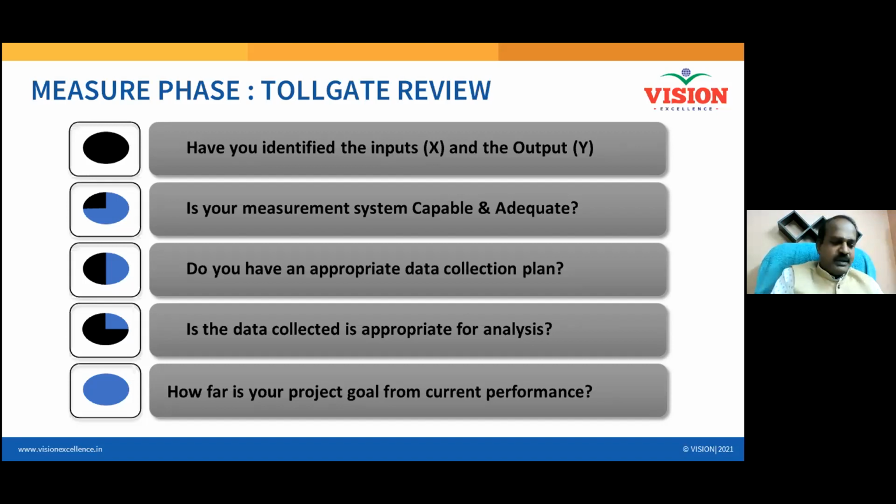In the same way, when you collect data, let's say from 100 to 110, all your readings are going to be from 100 to 110. Within the 100 to 110, how many readings is your system going to give you? That will talk about the adequacy. And suppose my resolution is 0.1, between 10 and 11, how many readings are possible?